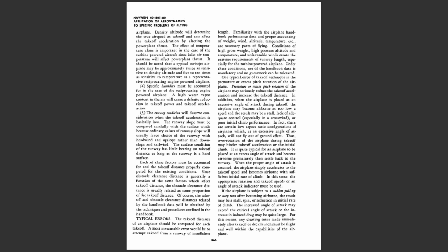In fact, there are certain low aspect ratio configurations of airplanes which, at an excessive angle of attack, will not fly out of ground effect. Thus, over-rotation of the airplane during takeoff may hinder takeoff acceleration or the initial climb. It is quite typical for an airplane to be placed at an excess angle of attack and become airborne prematurely, then settle back to the runway.